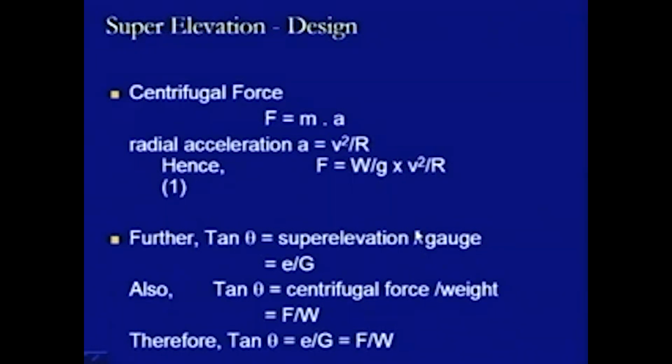Now, we come to the design aspect of super elevation. How do we design the value? The centrifugal force is defined as F equals m multiplied by a, where a is the radial acceleration and m is the mass of the body, and this radial acceleration is computed as v square divided by r.